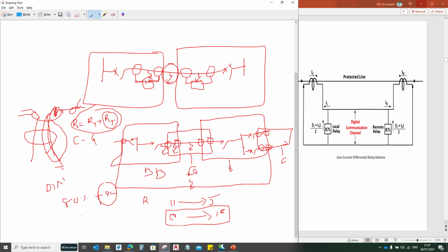So that's the reason, to detect this high resistance earth fault, we employ backup earth fault protection. This earth fault protection generally has suitable setting parameters to detect the resistance of the towers in addition to the transmission lines, and it will trip the circuit breakers.